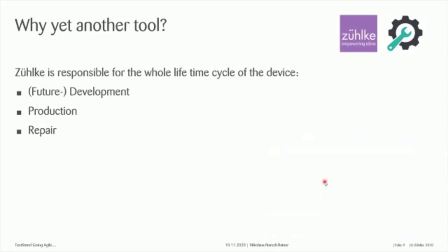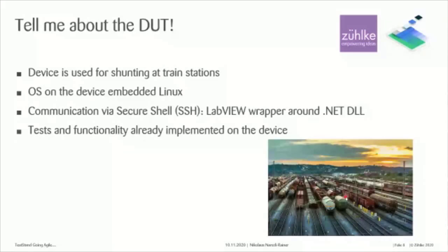So first of all, the device is constantly on the outside. So that means we are based in Switzerland. So in the winter we get snow, we get rain a lot. That means the devices are basically constantly on the outside, and also in summer there's basically no shadow. So the devices range from say -10 to 15 degrees Celsius to up to 40, 45 degrees. So there's a big chance that water condenses within the devices. This is hard to prevent.